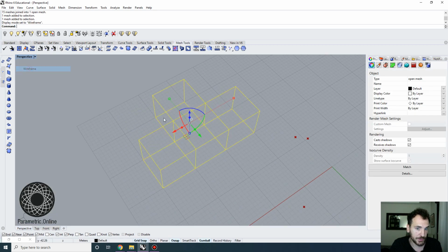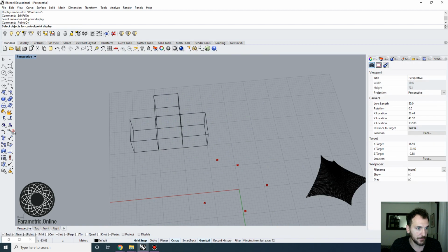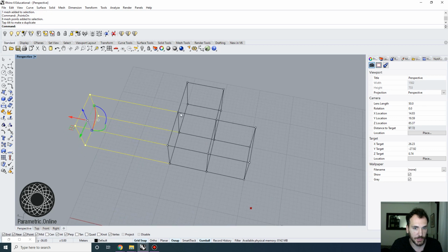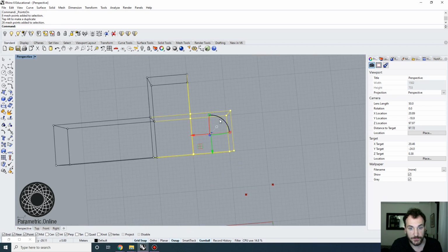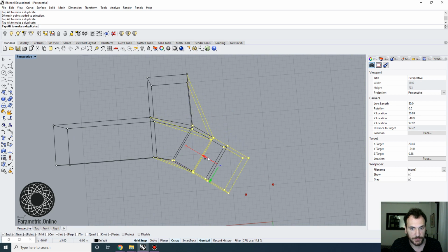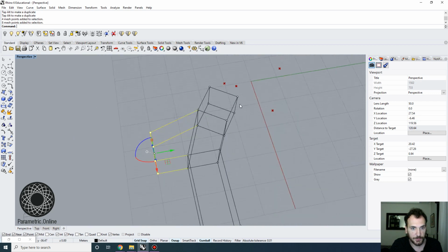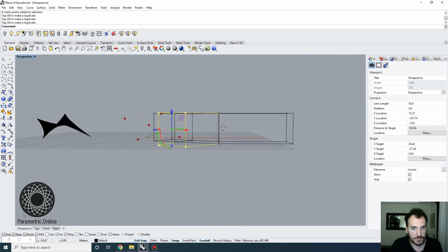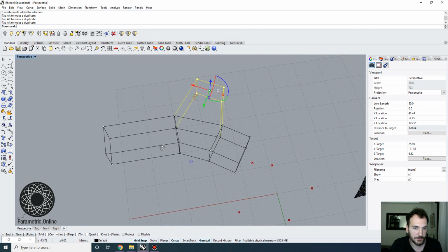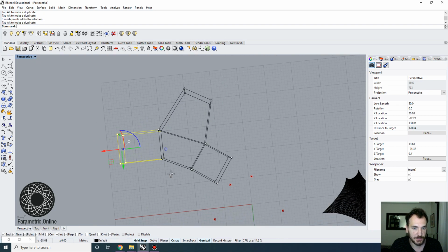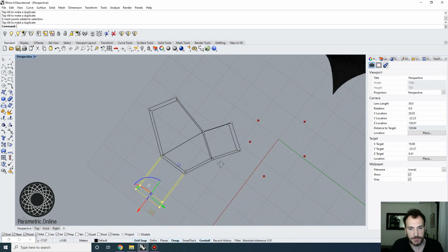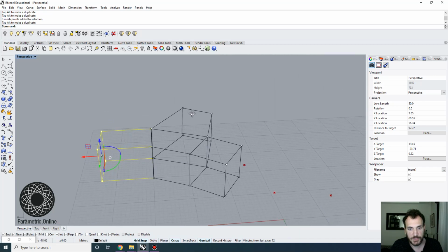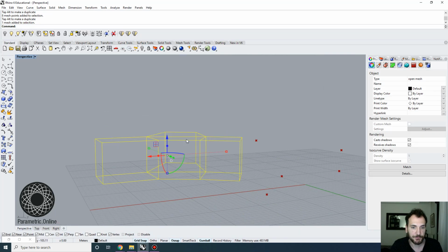But I'm going to make it a bit more interesting. So I'm going to go to the Standard tab, turn on these points, and we're going to play around with the location or the orientation of these points, so we can turn it around a bit. The way I'm approaching this task is, when I'm adding more geometry, I'm also thinking about how it will connect the topology, right? So imagine that this is kind of like a branching geometry, so you need to orient the mesh faces in such a way that the geometry will be tessellated in the right manner.